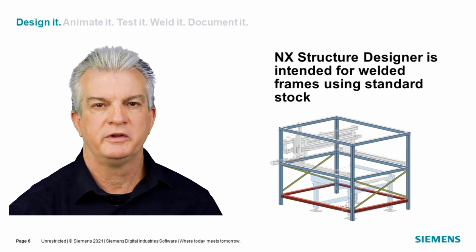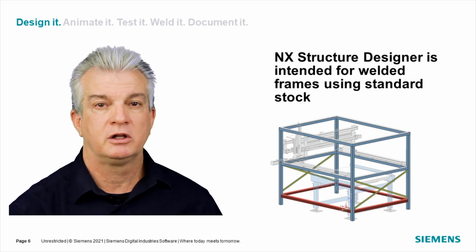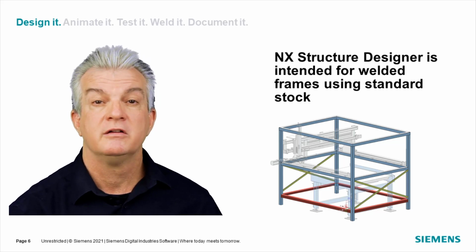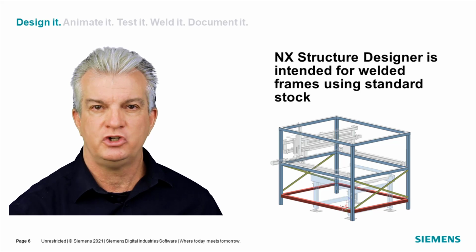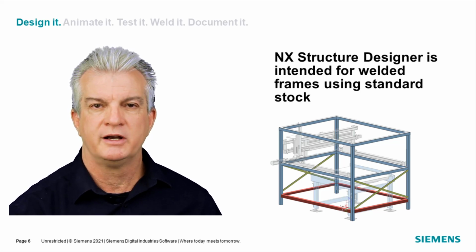NX Structure Designer was designed to alleviate a lot of those issues. It's intended for welded frames that are made from standard stock. We have a great 3-click cage command, rules-based member placement and corner definition so you get the right answer out of the box. We have an extensive library filled with different shapes, sizes, and materials. You can also turn a visual reporting option on to see exactly what stock makes up your frame.